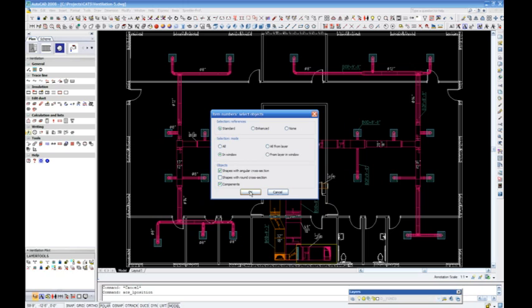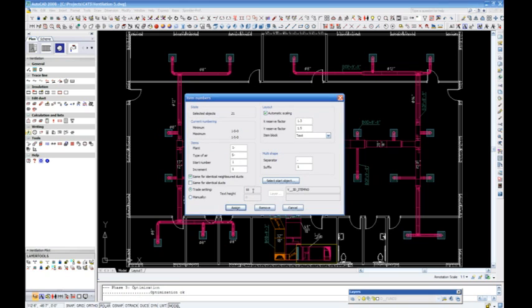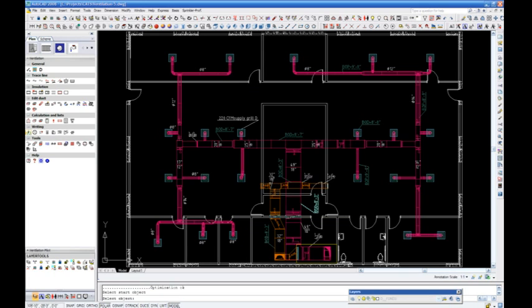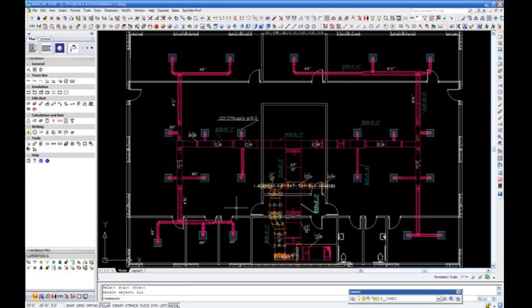In the C.A.T.S Commander, you can assign item numbers of duct or fittings on the drawing. Here we select the return air system. "21 pieces are found." We will now assign the type of letter, R for return, and select the start object. We can then assign the number sequence we choose to use.